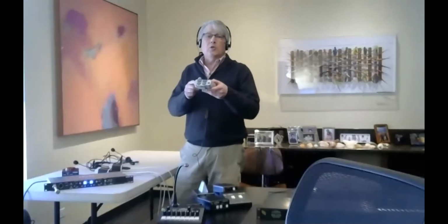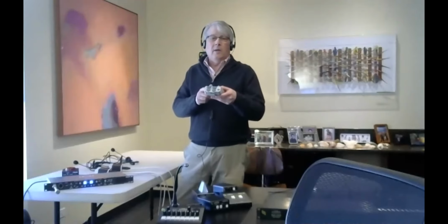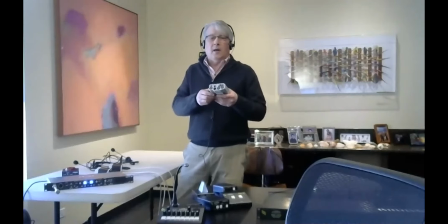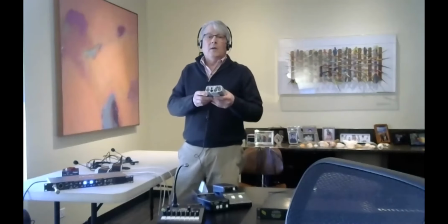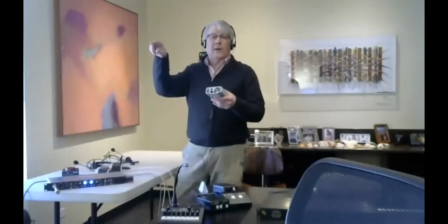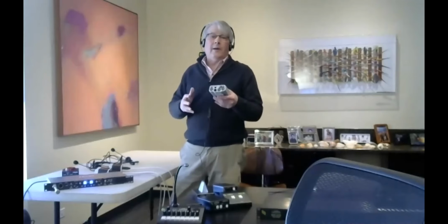person, this is a 2-channel analog belt pack from RTS called the BP325, very common on broadcast trucks. And what they do is over a single XLR, Stan Hubler and another guy, very clever, who developed this, they put 2 channels of audio over 1 cable. They put common on pin 1, power with audio superimposed. It's old amplitude modulation. You're just taking DC and you're putting the analog waveform on it. And then on pin 3, it's only channel 2 audio. So over a single XLR, analog 2 channels, they call it the TW or 2-wire, don't ask me why, 2-wire